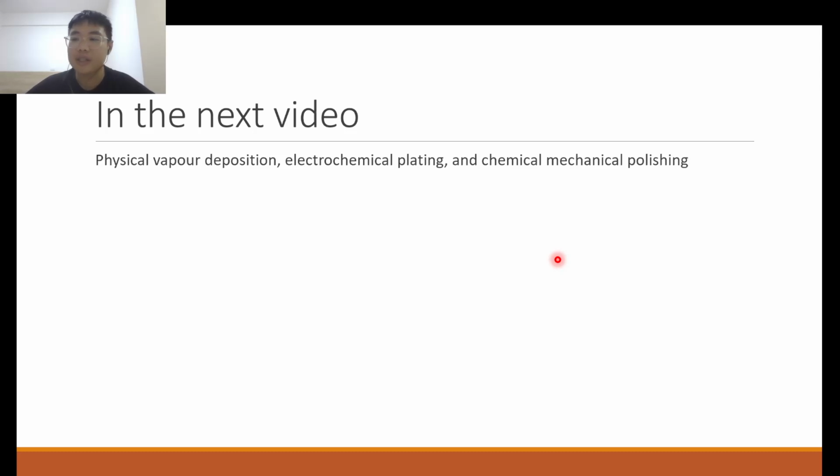Okay, so in this video, I've covered this whole idea of etching, dry etching, also known as plasma etching. In the next video, I will probably cover physical vapor deposition, also known as sputtering deposition. I will also cover electrochemical plating, and because of the close link between electrochemical plating and chemical mechanical polishing in the Damascene process in the back end of line, I will also cover CMP in the same video.